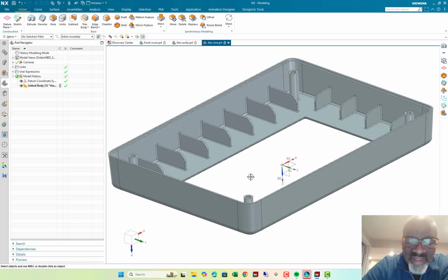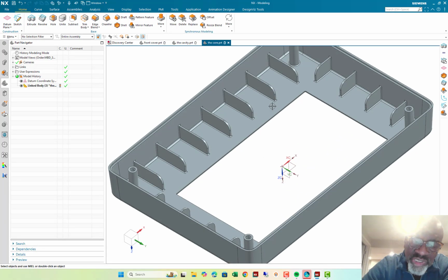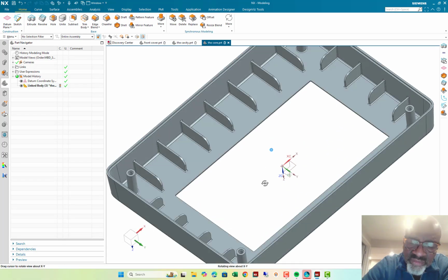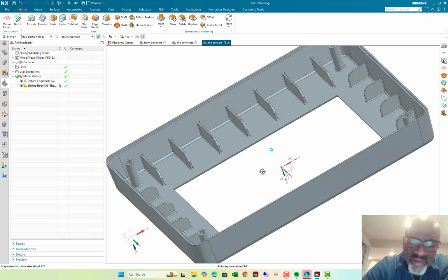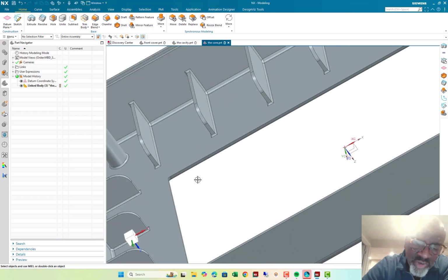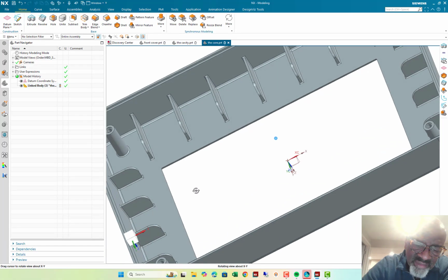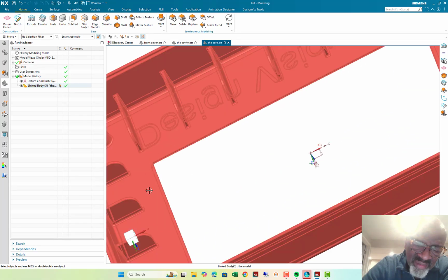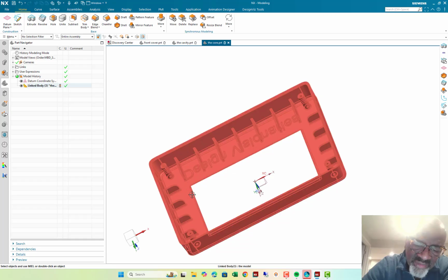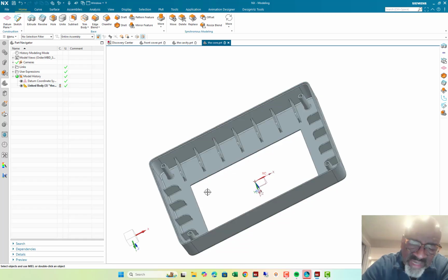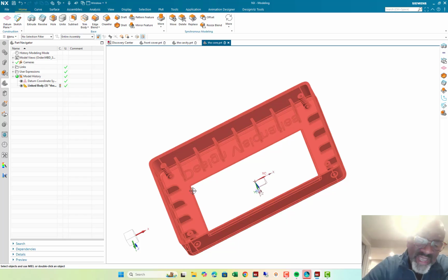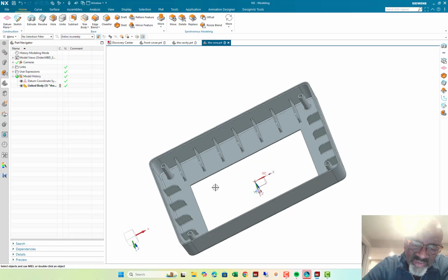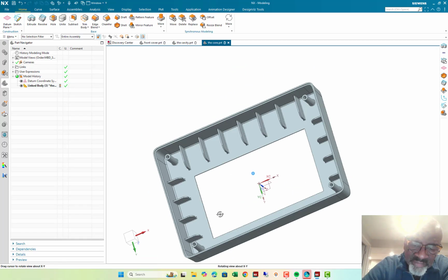So now I have to have a protrusion that looks like all of this. And the shutoff is right here, where I had that first extrusion there, the shutoff, meaning all of this geometry has to come up to the level of this plane.